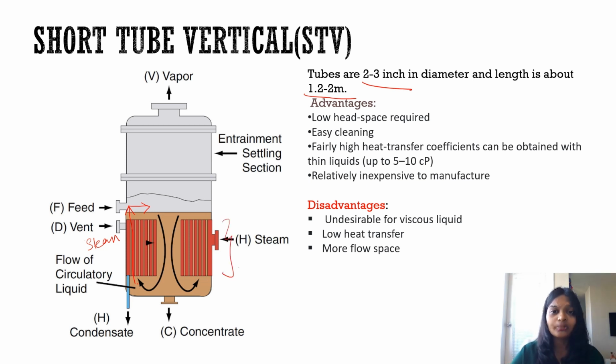Now talking about the applications, this can be used for clear fluids, or crystalline products if a propeller is used, or for a non-corrosive liquid and mildly scaling solution. Since tubes are involved, we cannot use a very highly scaling solution.